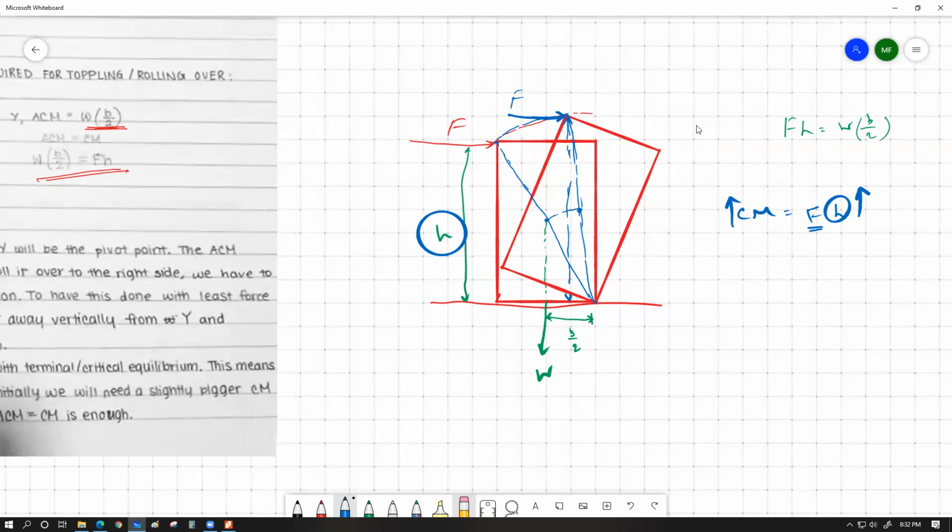as the center of gravity moves, the weight is working at the new position. But what is happening to the perpendicular distance of the weight from the pivot point? মানে হচ্ছে এই যে নতুন ডিসটেন্সটুকু, মানে হচ্ছে এই যে এটা হচ্ছে ওয়েট ওয়ার্কিং পয়েন্ট, এখান থেকে আমাদের এই পয়েন্টের ডিসটেন্সটা আগের থেকে কমে যাচ্ছে না? At the initial position, the perpendicular distance was B/2, but as the object keeps on rolling, the perpendicular distance of the weight from the pivot point is slowly becoming smaller, because this weight arrow is slowly moving to the right. ঠিক কিনা? বুঝতেছো?